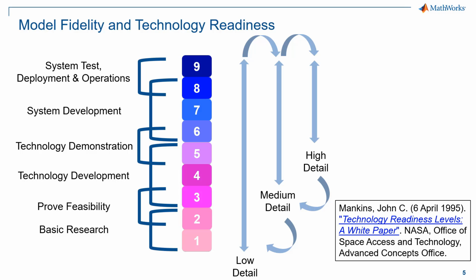As your technology matures, then simulation models that capture more specific technology attributes will be created. For example, you may incorporate models of actual technology types, such as permanent magnet synchronous machines with field-oriented control. But at the medium fidelity stage, you may still not have vendor-specific information on physical components and control components. A high-fidelity simulation model would have vendor-specific architectures, including specific parameterization of physical components and control system architectures. The model could also include detailed power electronics, thermal and cooling systems, and communication protocols.